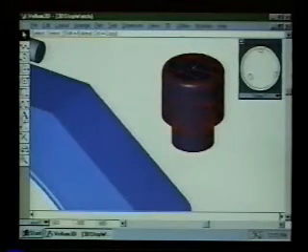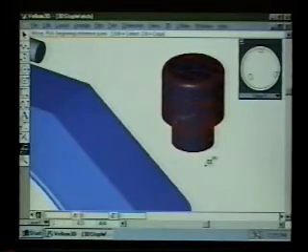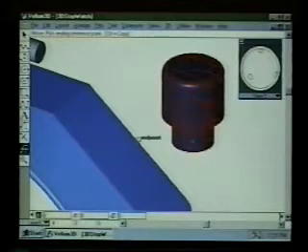So now we'll grab the move tool here, and I can highlight this thing by touching the bottom curve, and there I see it will highlight the word center for me. So now I can click on the bottom center to indicate my beginning point, click and release, and then I can go over to the face here and touch the midpoint and get an alignment across the face in that direction, and come up here and touch the midpoint up there and get an alignment in that direction, and come to the intersect right in the middle of the face, and I can click and it will position the button right onto the center of that face. So now we've located the center of the button onto the correct location on the face.